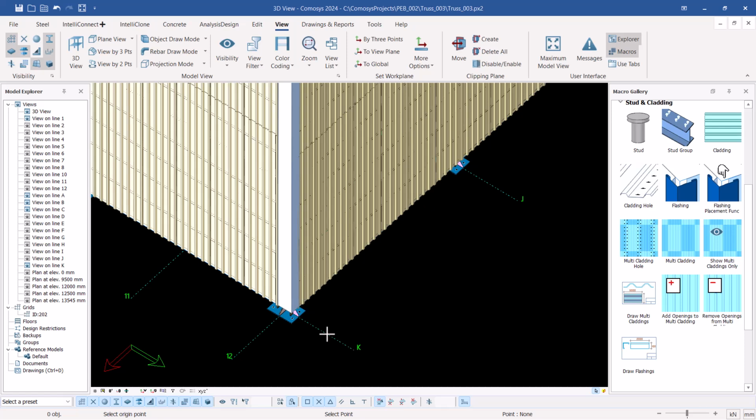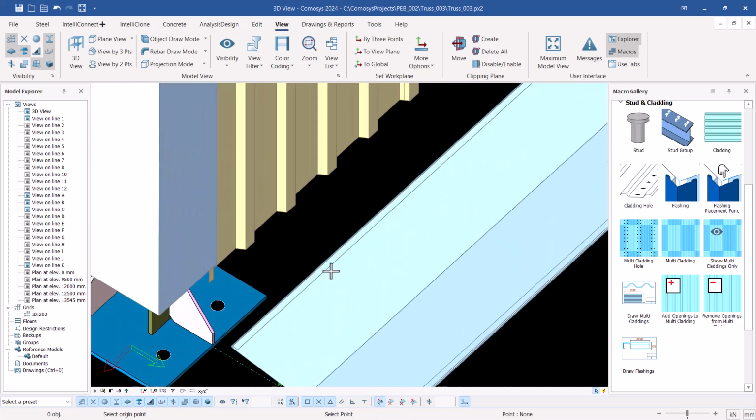and to create the flashing. So let me snap there and move all the way to that end there, and just mouse over, place my cursor right there, and make sure it is straight, because we don't want to create something that is diagonal. And let me just right click, and we have our flashing in place.